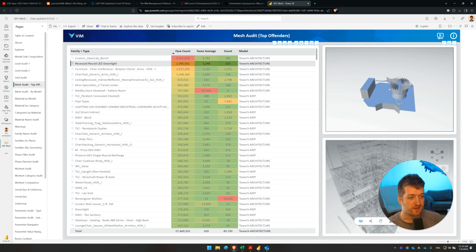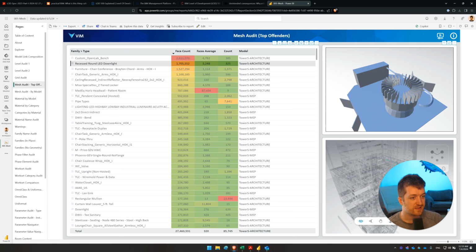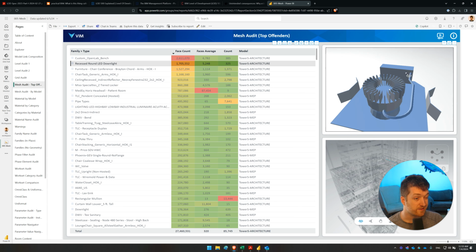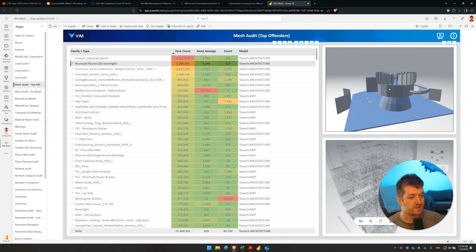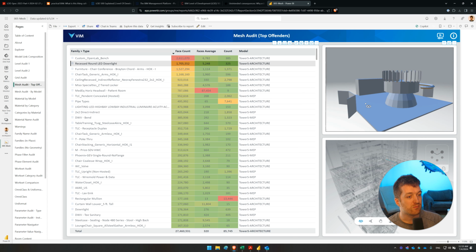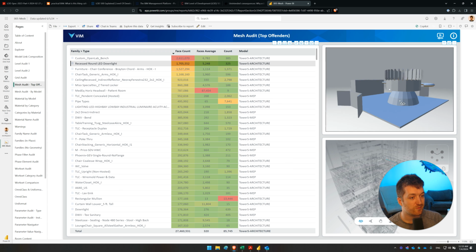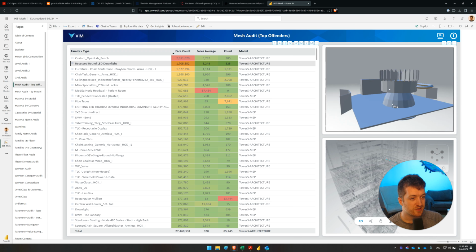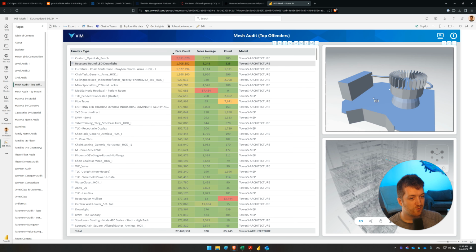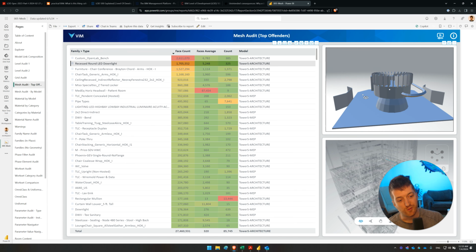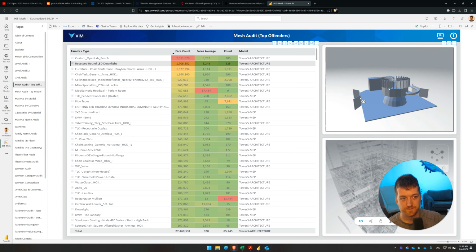And same thing with this light, right? Nobody needs to have this entire heat sink and this wire, for example, or even these things. These can just be little blocks that show us, hey, if there's a pipe in there, it's going to be a problem, but nobody's doing a rendering inside of the ceiling. This level of geometry here really doesn't matter. This could have been just a very simple cylinder with a couple boxes to show where there could be interference problems.